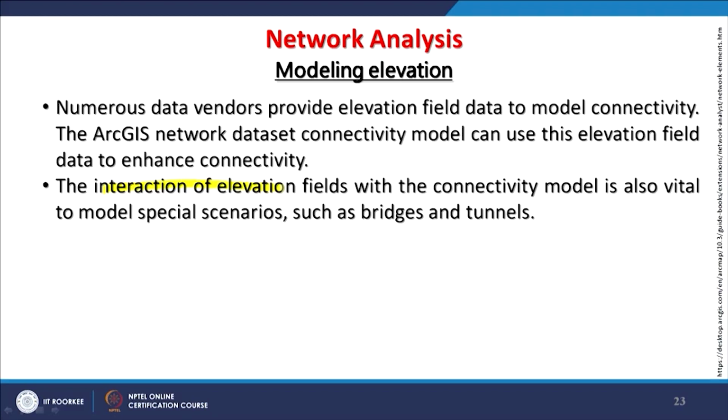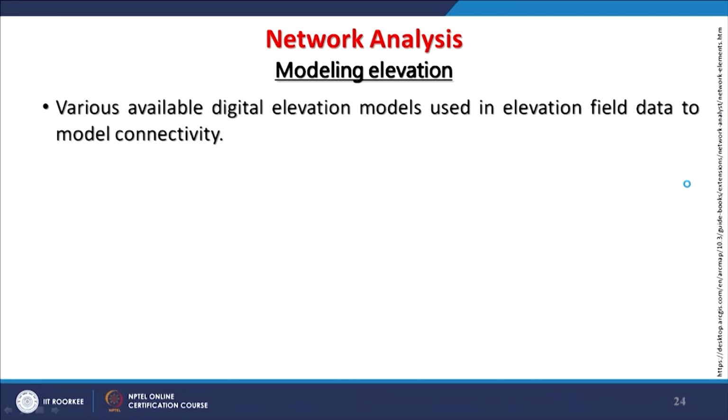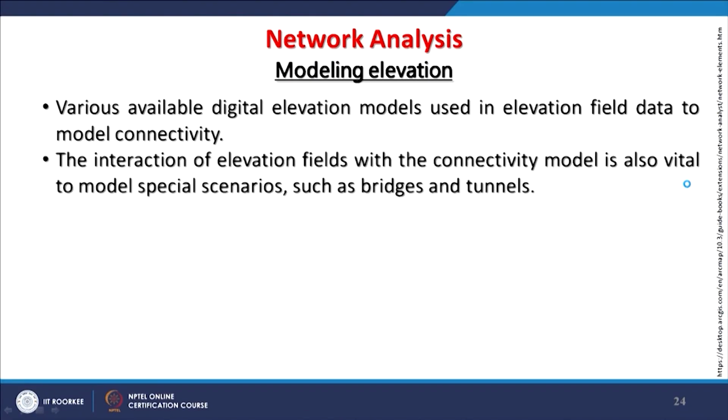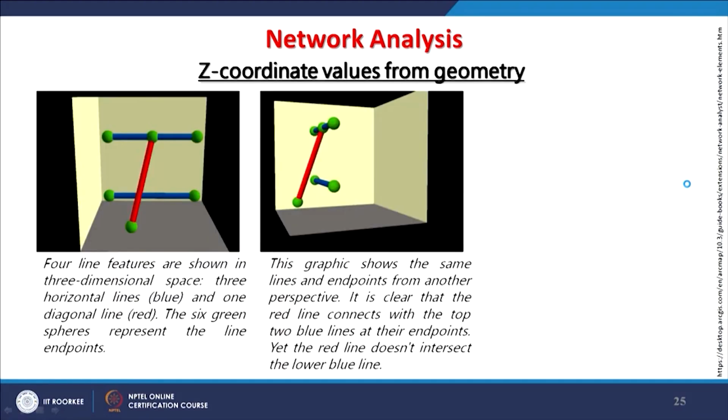So the interaction of elevation fields with the connectivity model is vital to model spatial scenarios such as bridges or tunnels. Further, various available digital elevation models can be used in elevation field data to model connectivity, but only in case things are moving on the surface. But if you have subsurface conditions like underground metros, then digital elevation models cannot be employed. Then that elevation information has to come from other sources. So the interaction of elevation fields in our network database with the connectivity model is vital to model these bridges and other